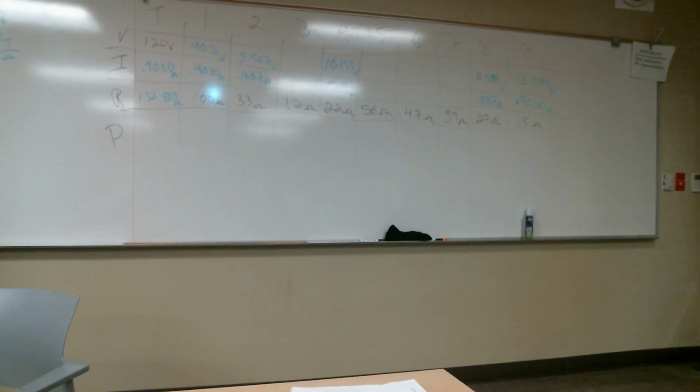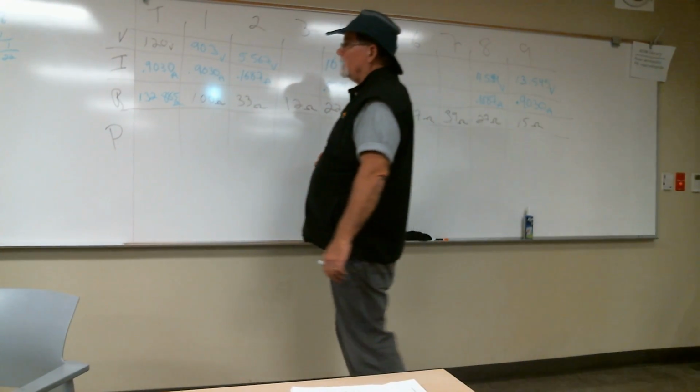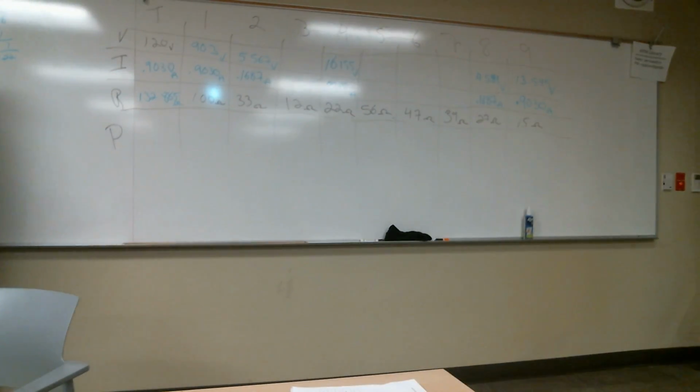So I'm going to drop 5.567 here, and I'm going to add 4.554 volts here to get to the new node voltage. So if I've been keeping a running tally, well, it looks like I have been keeping a running tally. Okay, so 13.545 and 4.554, 17, 18.